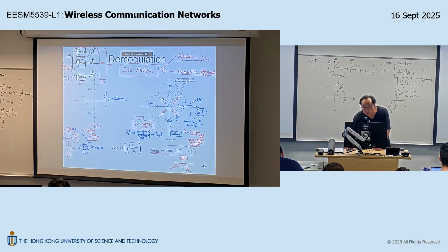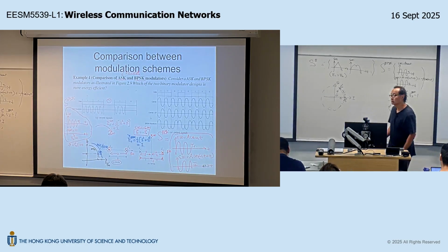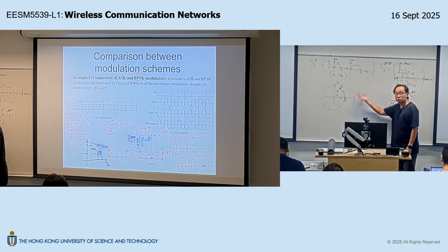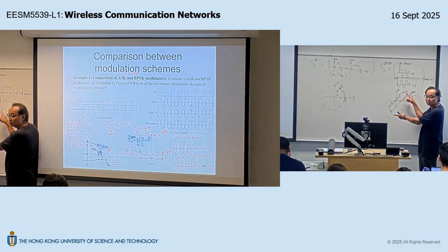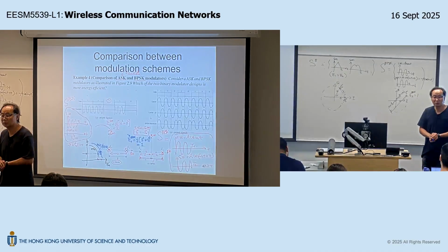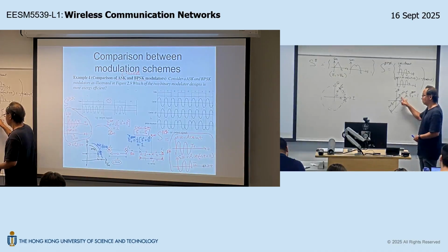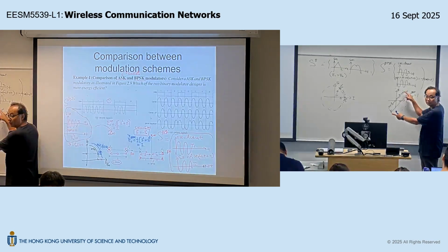So once you have this kind of geometric insight, the insight is very simple. Error probability is just determined by the overlapping area between these imaginary noise clouds. Once you have this intuition, then you can do a lot of analysis based on this simple geometric intuition. Okay, and from these 3 examples, you can also deduce that this is actually the best possible case to put 2 points on a constellation in the 2-dimensional space, right? Because you pay 1 unit of energy cost to separate these 2 points, right?